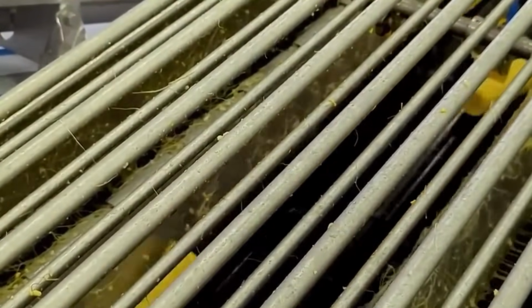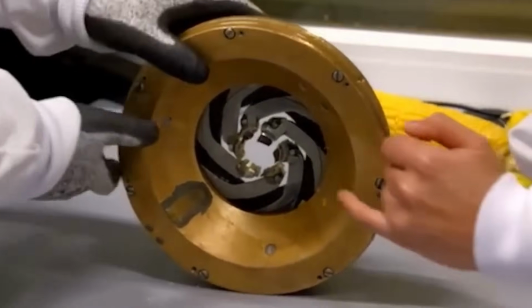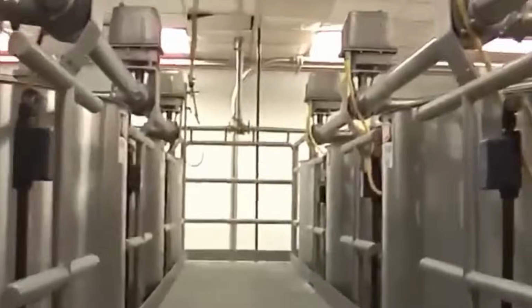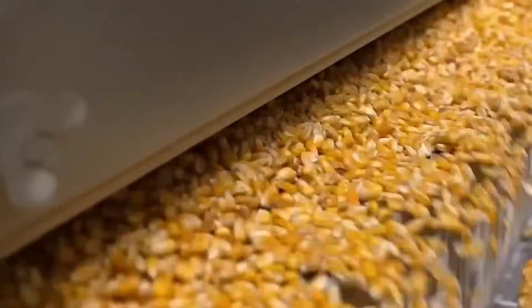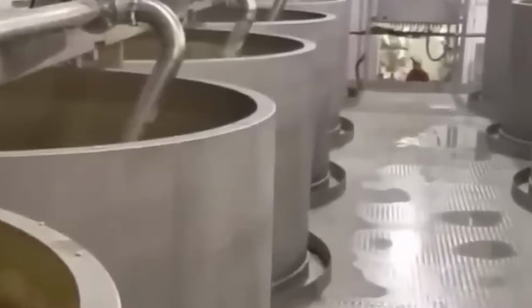This is a horizontal, cylindrical tumbler fitted with internal flights that lift and rotate the chips as they pass through. Seasoning application occurs via two systems: dry powder feeders and liquid slurry sprayers. The dry powder feeder consists of a vibratory tray with variable speed auger dispensing seasoning mix at a calibrated rate. Liquid slurries containing oil-based flavor carriers are sprayed using pressure nozzles fed by gear pumps. Flow rates are adjusted in real time based on chip throughput measured by load cells at the drum's infeed.